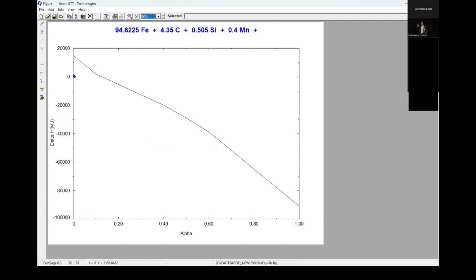We have started with 1300 degrees C liquid metal, and we have 1 ton of CaO, 18 tons of cooling scrap. If we have as final conditions 1600 degrees Celsius without blowing any oxygen in, of course, you need to give heat to the system. So we have a positive delta H. But the more oxygen you blow in, the more heat you produce and release by the burning of carbon and then also the metals. And therefore, you then have an exothermal process as soon as you blow in a bit more.